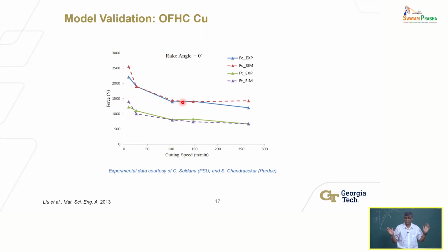Those two I can measure using, I think yesterday I mentioned that there are these sensors available called piezoelectric force dynamometers that you can mount the workpiece on and cut, and you can measure the forces. So these were measured that way, okay? Measured by somebody else, collaborators of ours.